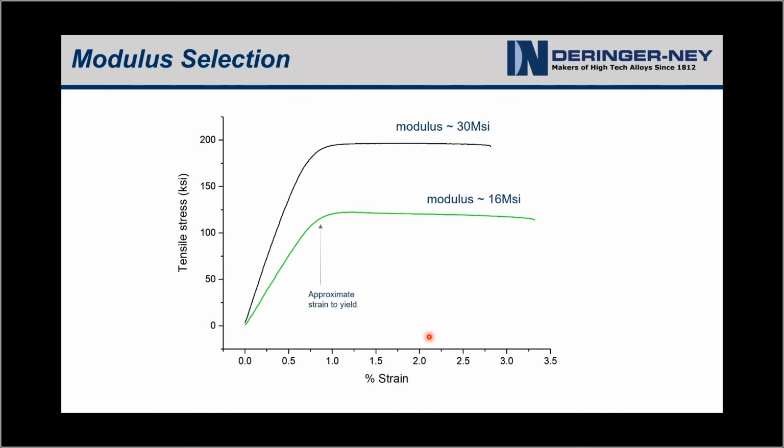One of the reasons is that a lot of electrical contact systems are really defined by strain. So they're strain-driven designs that are not operating on a principle of, okay, well, it's going to be a floating contact that will always be at a certain constant force, right? So if you look at these two materials, their approximate strain to yield is similar. So I'm not going to worry too much until the end about starting to understand the interaction of yield strength,